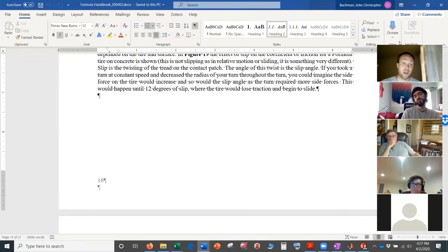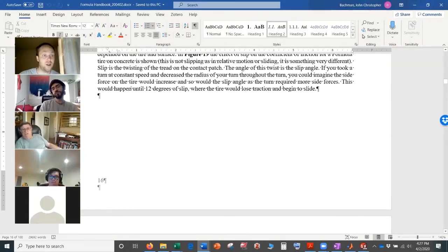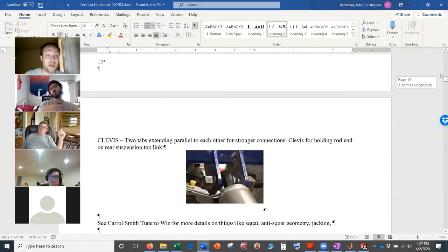The Baja, we do a lot of oversteer because we have a rear differential, we have a rear solid axle. So our wheels can't spin at different rates in a turn, our rear. So they suck at turning. So we say, screw it. Let's not have the rear wheels turn. Let's just whip them out, right? That's basically what I see with a lot of the Baja teams. When they do tight turns, they just let their rear not do any of the turning and let it fly around. So that's one reason to make it narrower.